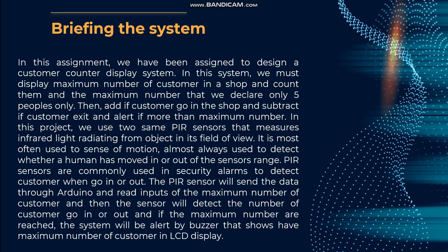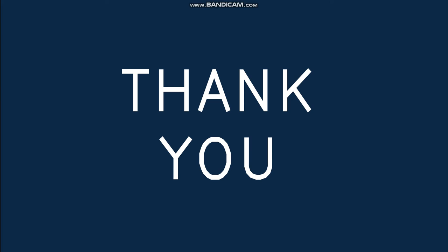PIR sensors are commonly used in security alarms to detect customers going in or out. The PIR sensor will send the data through the Arduino, which reads the input of the maximum number of customers, and then the sensor will detect the number of customers going in or out. And if the maximum number is reached, the system will alert by buzzer and show maximum number of customers on the LCD display. That's all from us. Thank you.